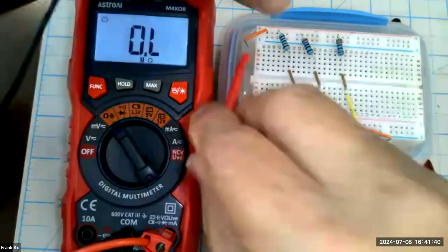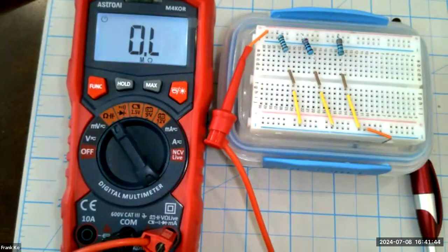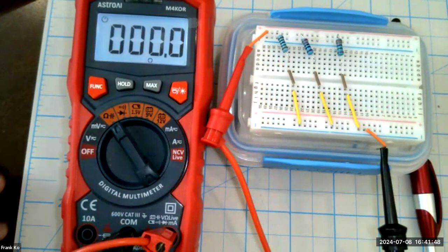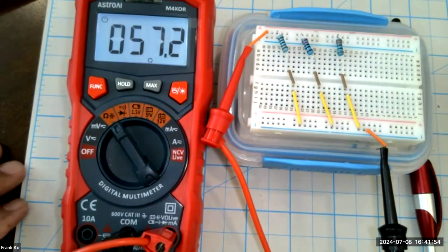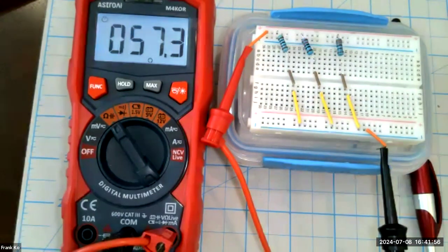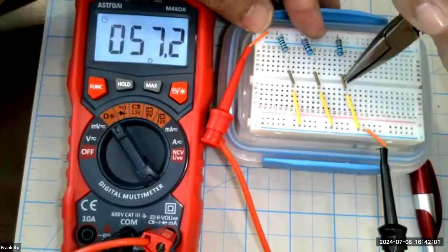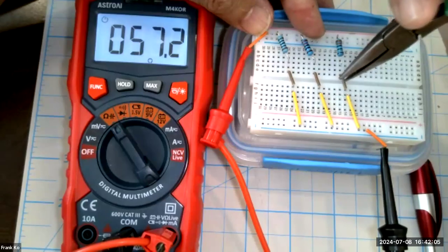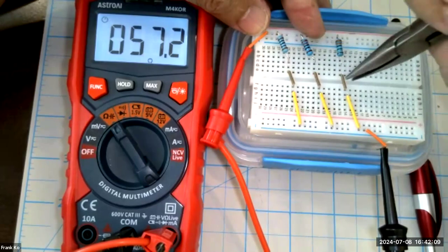Now, remember, you've already recorded these numbers in your journal, so we're just verifying what would happen if these scenarios presented a fault condition. So the first fault condition was leaving R1 parallel with R2. That says that something happened to R3. So either R3 burned out or R3's path was wrong. So I've got this nice jumper here.